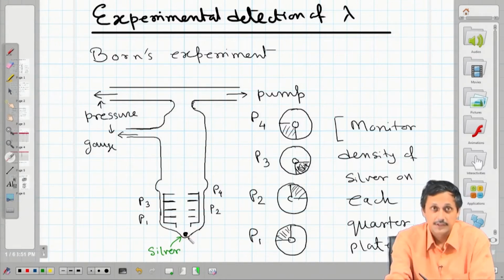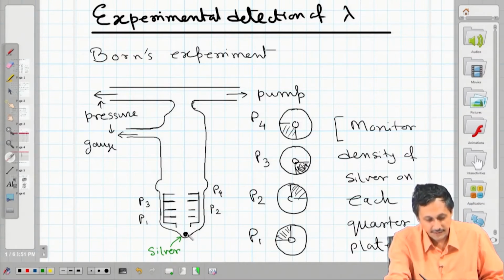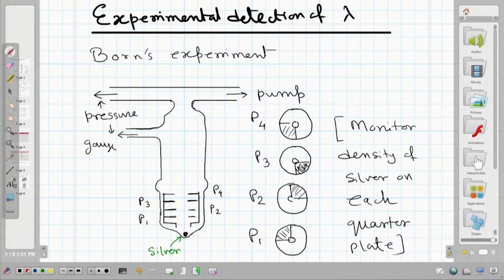So, as the temperature of this silver increases, the silver molecules start to evaporate. As the evaporated silver goes up, it goes through these 4 aligned holes, so that silver can essentially pass through, and in the process, as the silver molecules go up through the holes, they put a coating on these plates. This is a standard technique for vacuum deposition, and nowadays in our labs we routinely use such a technique to create electrodes. We have a vacuum, and a heated filament holding either silver or gold or aluminum, even copper or tungsten, and then the rest of the chamber is evacuated.